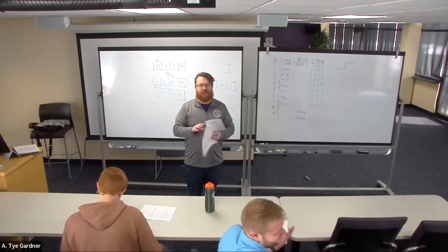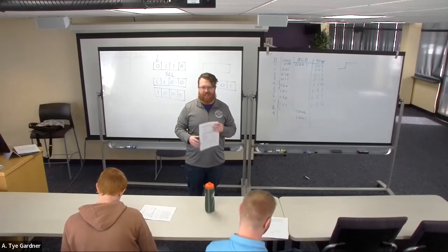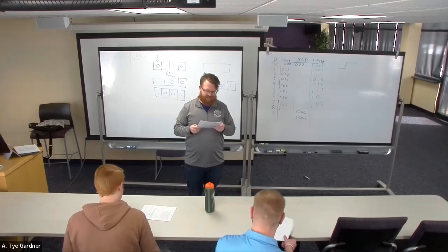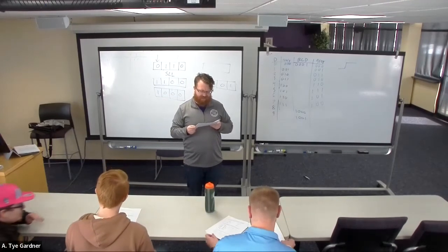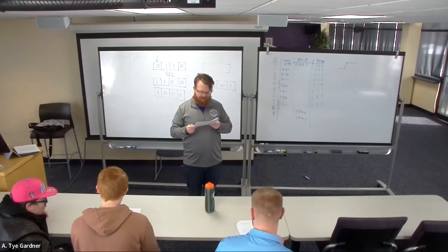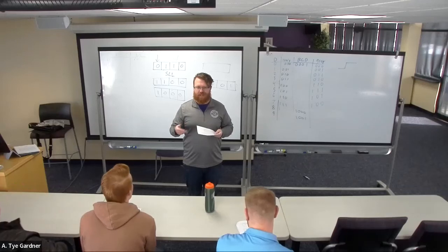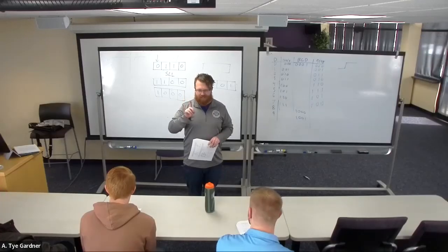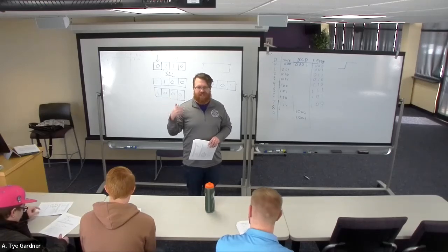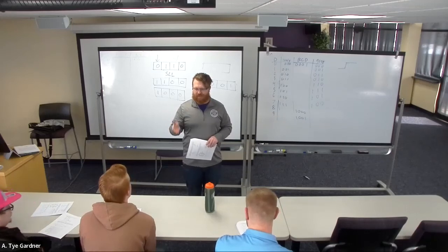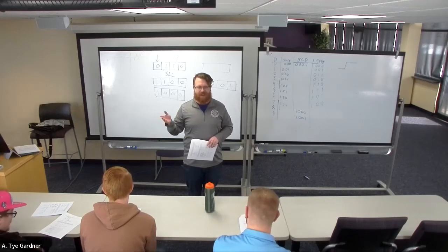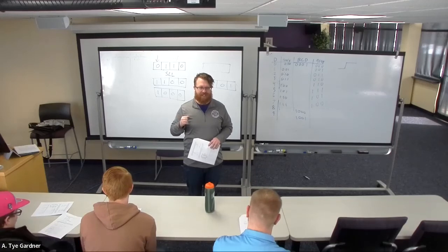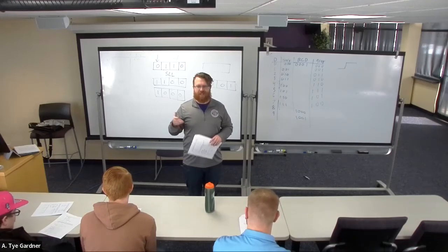So I will say the most points missed on this exam came from question number 15, where a lot of you overly aggressively applied stimulus to A, B, or A, C, and D, right? You only needed to change B once. Everything else was wasted effort, right? That's the point of testing for hazards. And guess what? I gave you the simplest possible version because it didn't matter if you went from 0 to 1 or 1 to 0. Either one generated a hazard with this XOR gate. So if you did the simulation right, it shouldn't have taken very much time.